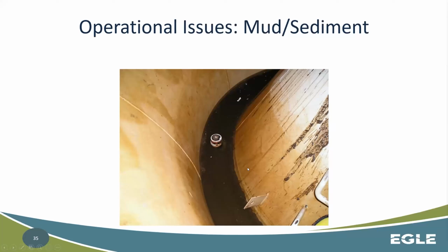So having mixers or diffusers or things like that, you're having good mixing and good turnover of your water in general, you might not have that settling out the same kind of way. So maybe keeping that in solution might be better, at least in terms of longevity of your water tank, and making sure you're not eventually, at some point, pulling that mud or sediment back into the system if it gets high enough.